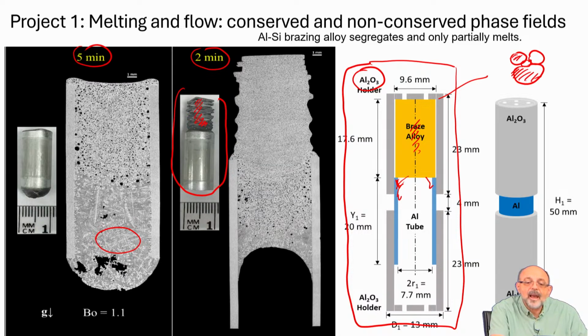Aluminum grains and gas inside, and then if you pull this liquid quicker than you can melt, you have taken out all the silicon, and you will not melt many of the grains. So you're left with small, if you were to magnify this, you will see the white little grains like here. Black things are the voids, right? That's the gas, and because of surface tension, there is melt around the grains that has solidified.